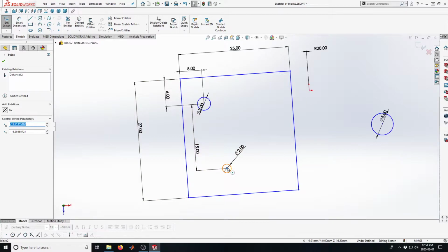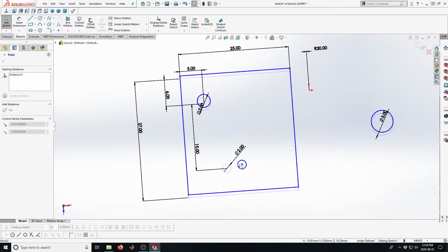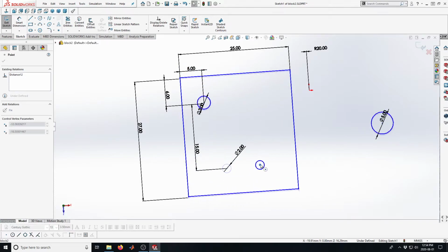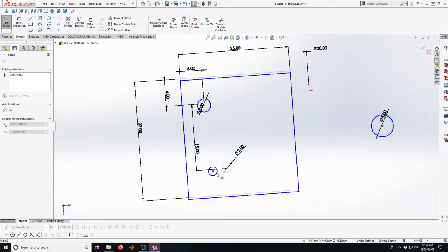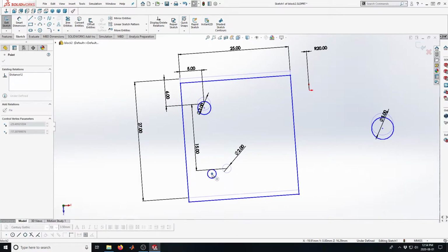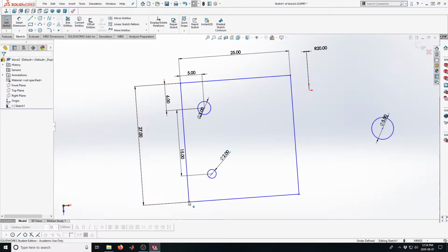The other thing that's interesting is you'll notice that the whole framework of the part is moving around. Well, I haven't actually nailed stuff down. I just randomly drew these in space. And that's okay in some cases, but let's try some relationships.